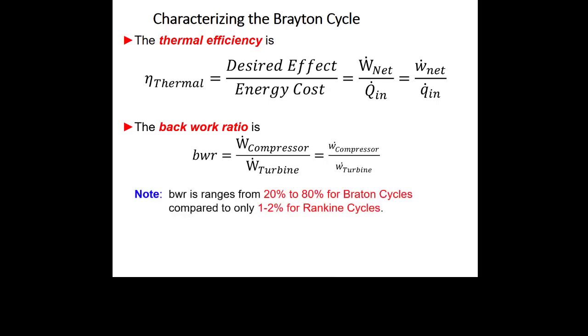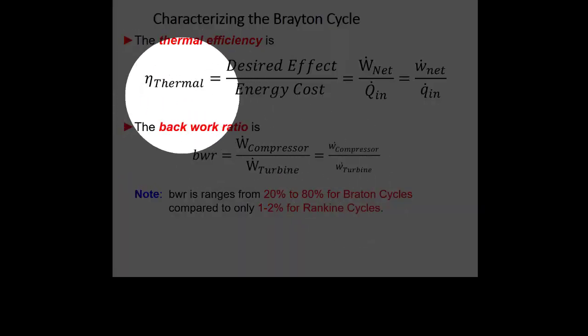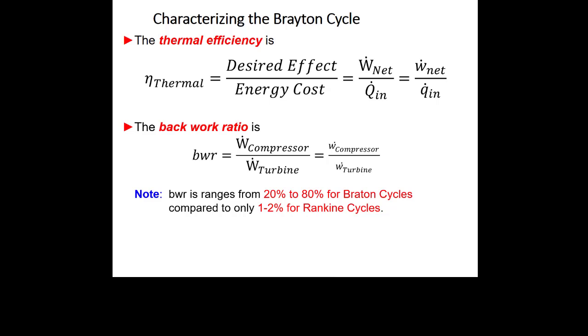Now it's interesting here because Rankine cycles are less efficient than Brayton cycles. So Brayton cycles have higher thermal efficiencies. Right? And we talked about the main downside of the Rankine cycle, or at least one of the downsides of the Rankine cycle, is that you have to cool that water down, right, from steam back to liquid water, which means you lose a lot of heat. Right? To cool the fluid down in a Brayton cycle when it's ideal gas, it doesn't need as much cooling, right?